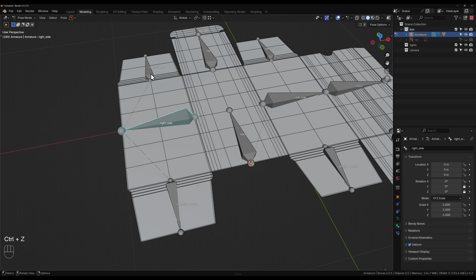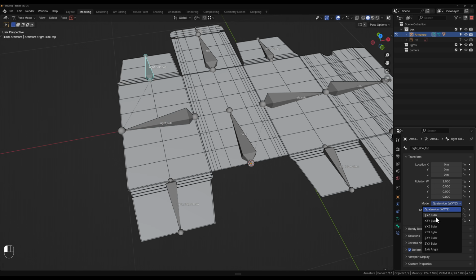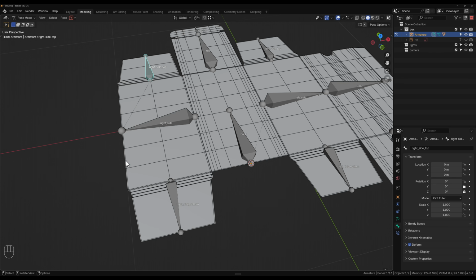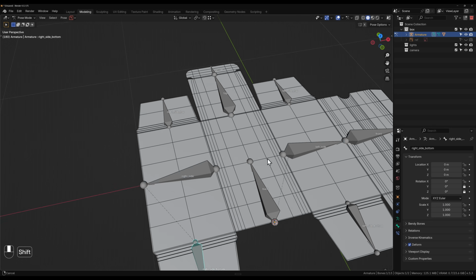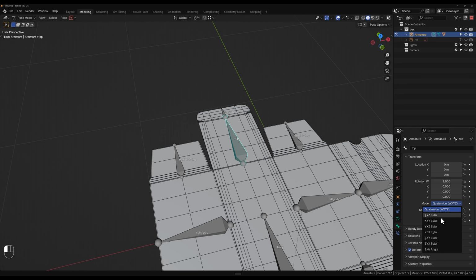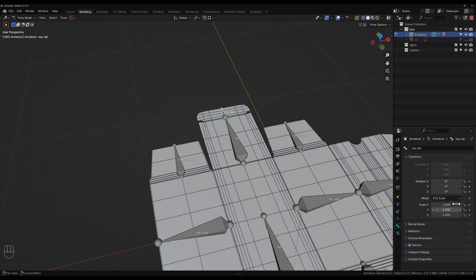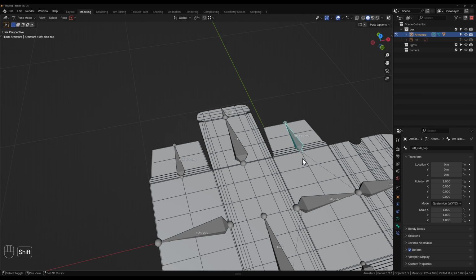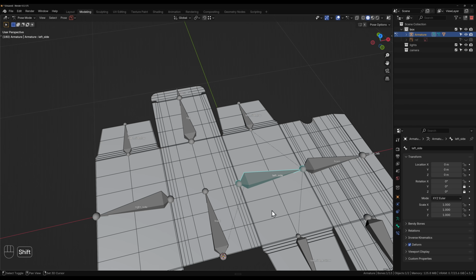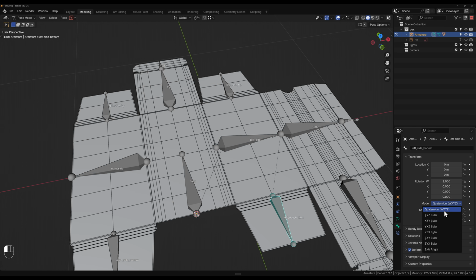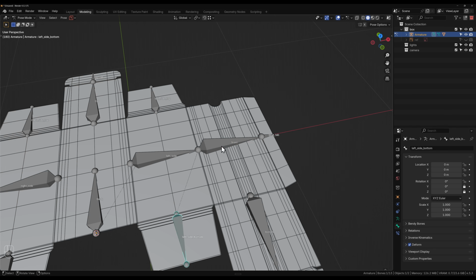And so we're going to do that for every single one. So we'll switch it to Euler, lock the other two, X, Y and Z, lock those two just by dragging across them. And every single bone that we do will be the same. Lock those two, grab this guy, lock them.